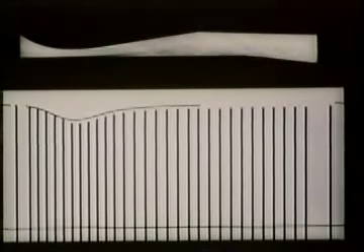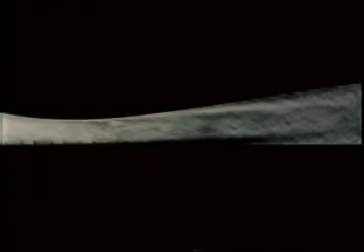Now let's go on to look at some properties. The object of the roughness is to produce small disturbances in the flow as an aid in visualization. There is no visible effect on the flow until the shock wave appears. Then characteristic disturbances called Mach waves appear in the region between the throat and the shock wave. These Mach waves, which originate at the edges of the tape, are evidence of supersonic flow in the diverging part of the channel.